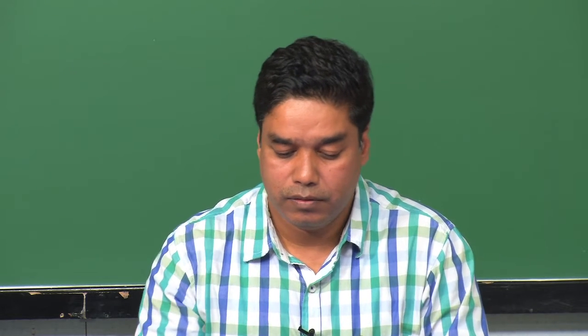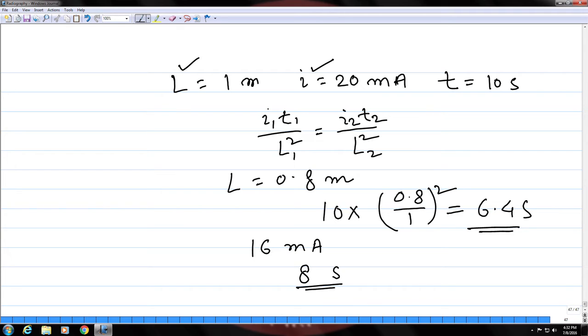Okay. So, like that based upon this particular equation, this is how we can find out for a particular tube current and particular sample to source distance what should be the exposure time. But here this is about the distance between the source and the sample.